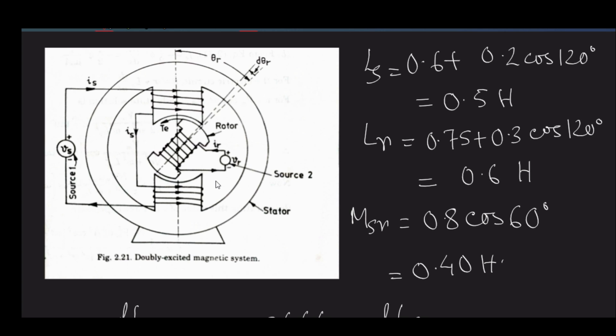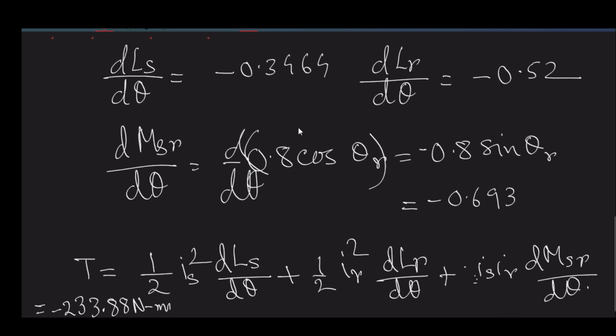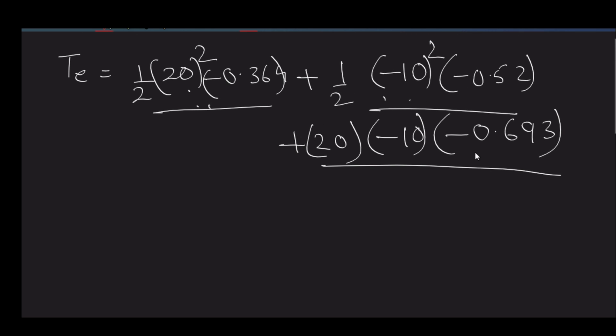And if you consider the first two players, once you cross 90 degrees, they are quite okay. Actually they cannot say much, their demand is very simple. They are only praying that please make sure the reluctance is minimum. That is the nature of the reluctance torque, but not the nature of this third term, that is due to mutual. This one always tries to align them as per the mutual current direction.